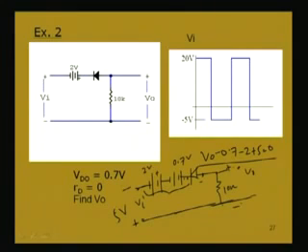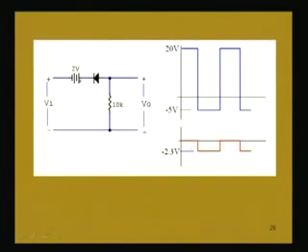From here we get V naught minus 2.7 plus 5 equal to 0. So, what is V naught? V naught is equal to minus 5 plus 2.7, which is minus 2.3. So, minus 2.3 volt you will be getting at the negative side.